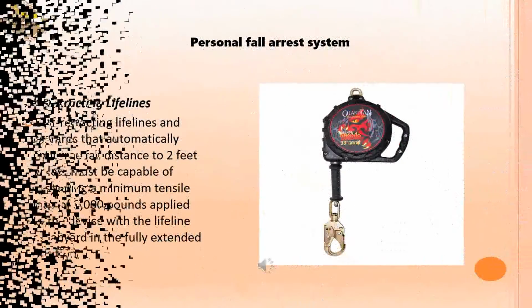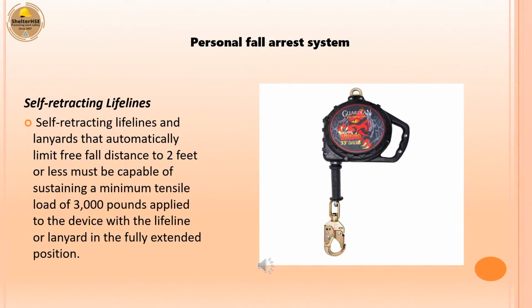Self-retracting lifelines. Self-retracting lifelines and lanyards that automatically limit free fall distance to 2 feet or less must be capable of sustaining a minimum tensile load of 3,000 pounds applied to the device with the lifeline or lanyard in the fully extended position.